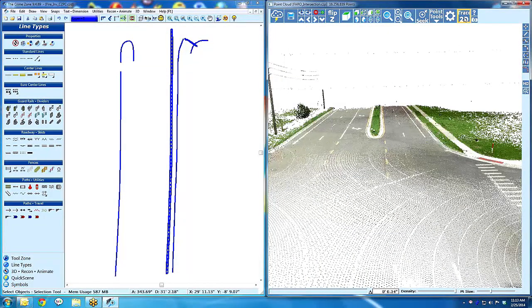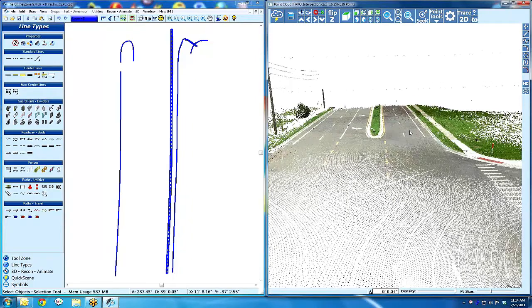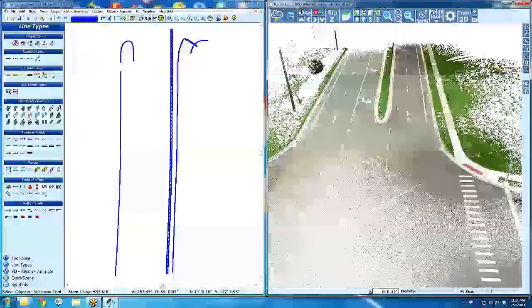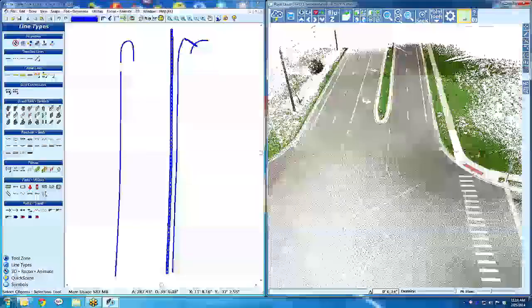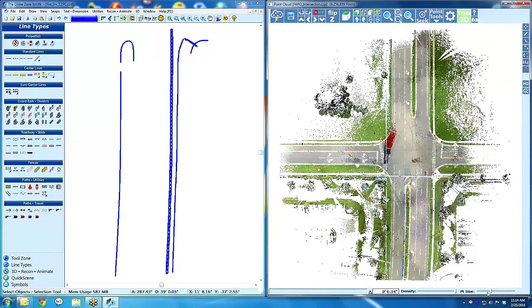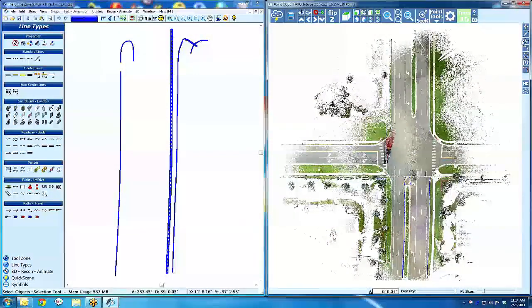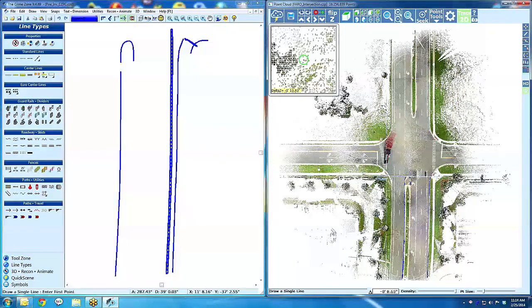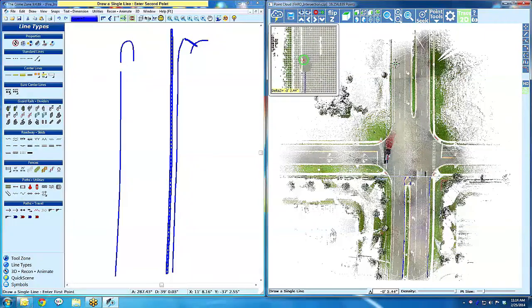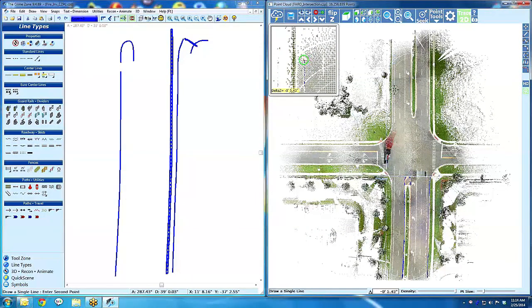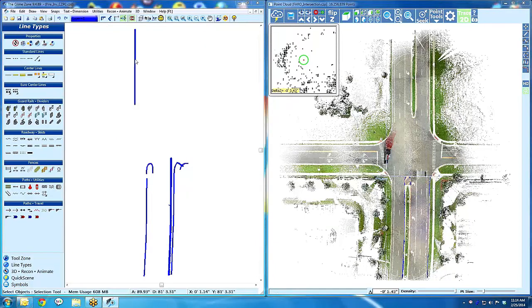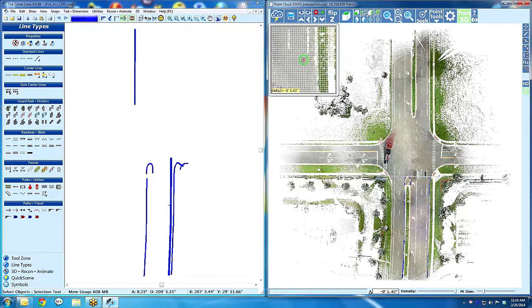And then the 2D trace mode that we talked about. Some people just want flat 2D diagrams. So what you saw us do in the room, but on a 3D intersection or something, many departments still just want a 2D diagram. Well, we just go into 2D trace mode and do a top-down view, and then they can bring up the mag window, start right on that line, and you're still snapping to the data. What it's doing is just zeroing out the elevation. There's no elevation anymore.